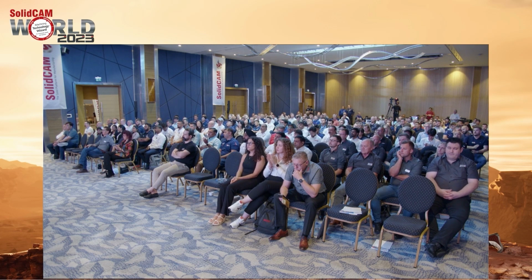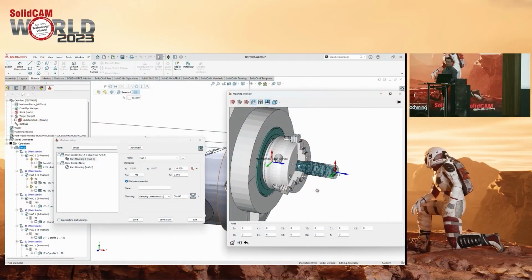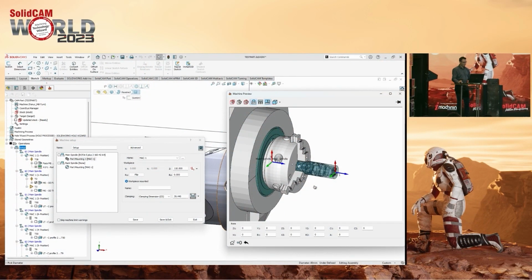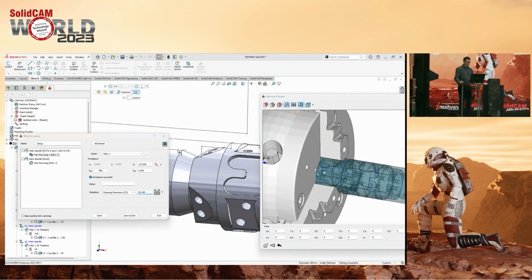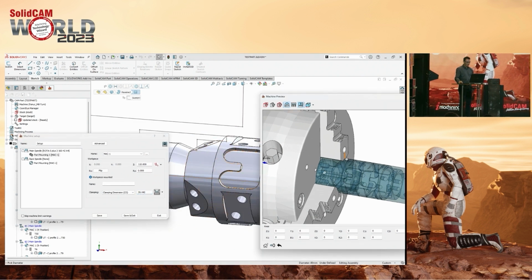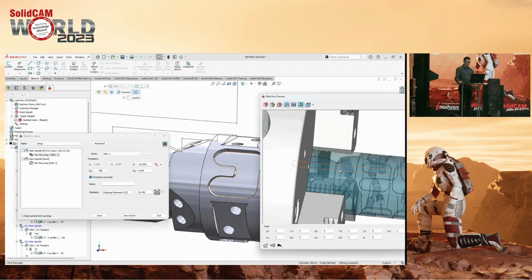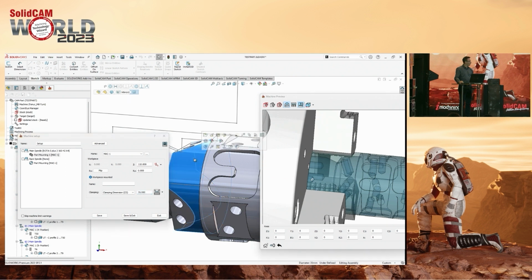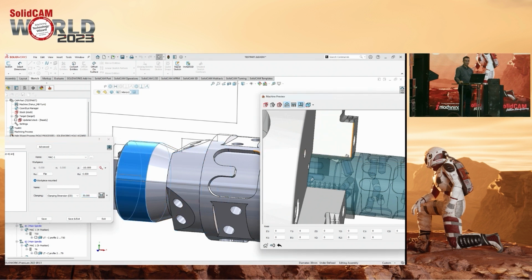In the same way, I can just place it on the sub spindle. I can define all those things. So all things are more or less the same. But let me show you another small technical thing. Not only that you can do it like auto close, but you can close it to any clamping dimension. So for instance, I can just click on this dimension over here, and I can click on this diameter. You can see dynamically how it changed. I can click on this diameter, and it's changed as well.